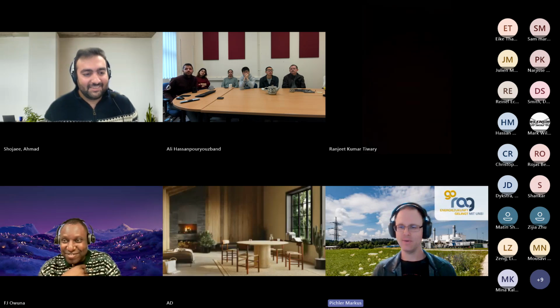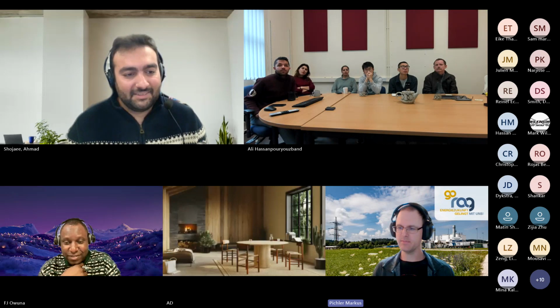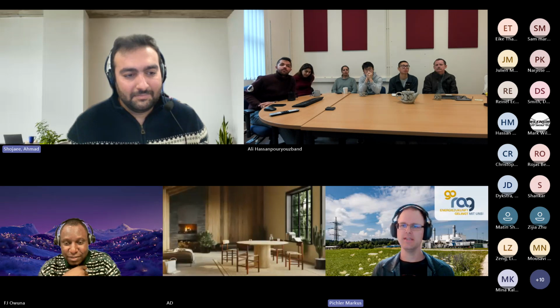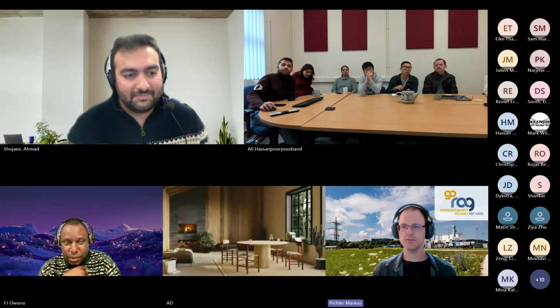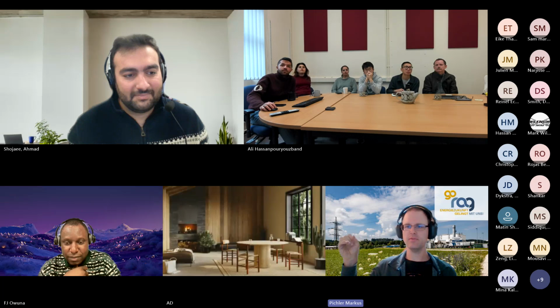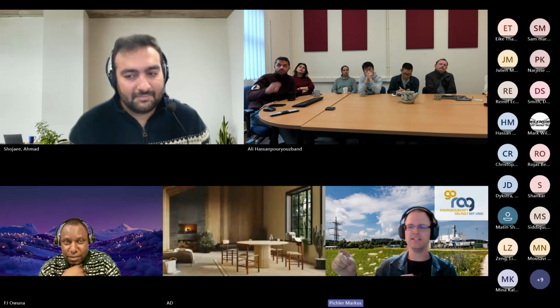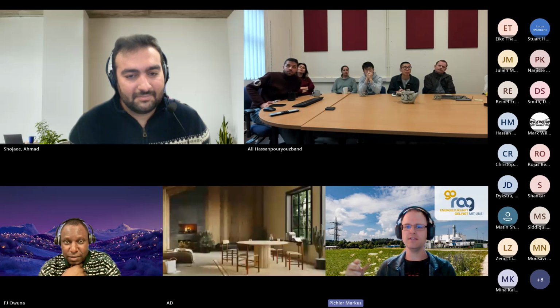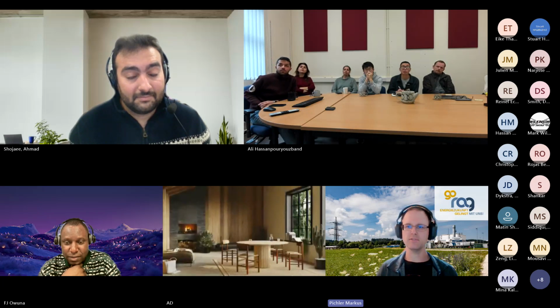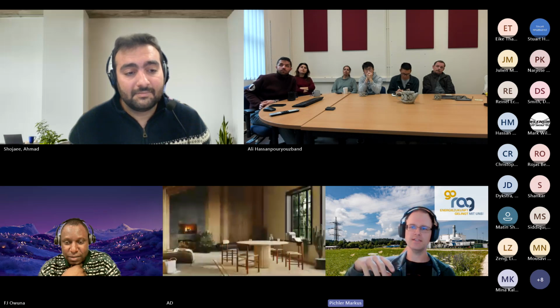Thank you. Well, actually, yes, we did measure the reaction rates in the laboratory as well as in the field. And you saw the clear difference between the laboratory, where we had high reaction rates naturally due to the smaller space, so the communication of gas and microbes is much better than in the reservoir, where you have a porous system where the communication is not that good. Therefore, the rate of reaction decreases by a factor of 100. So it's much, much slower than you see it in the reservoir.